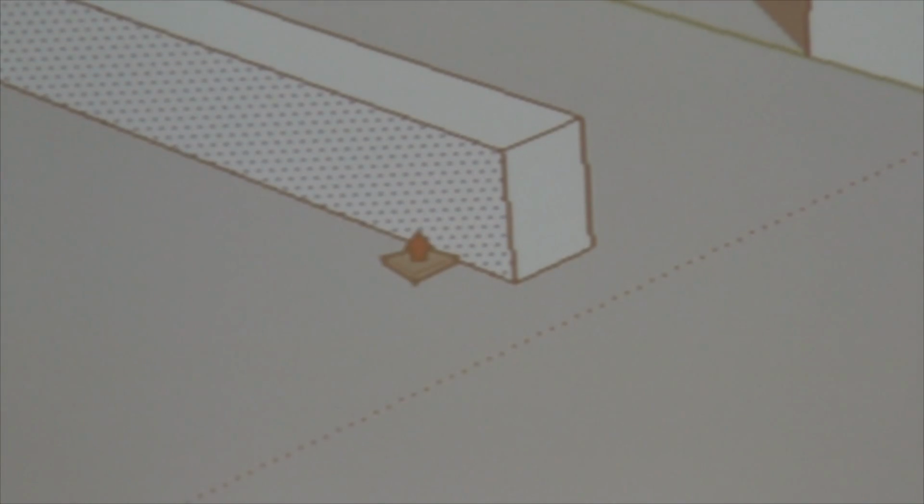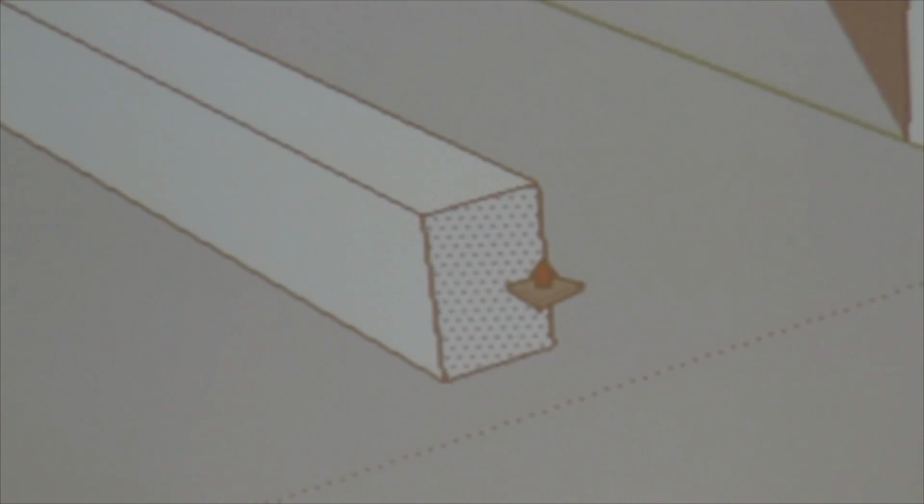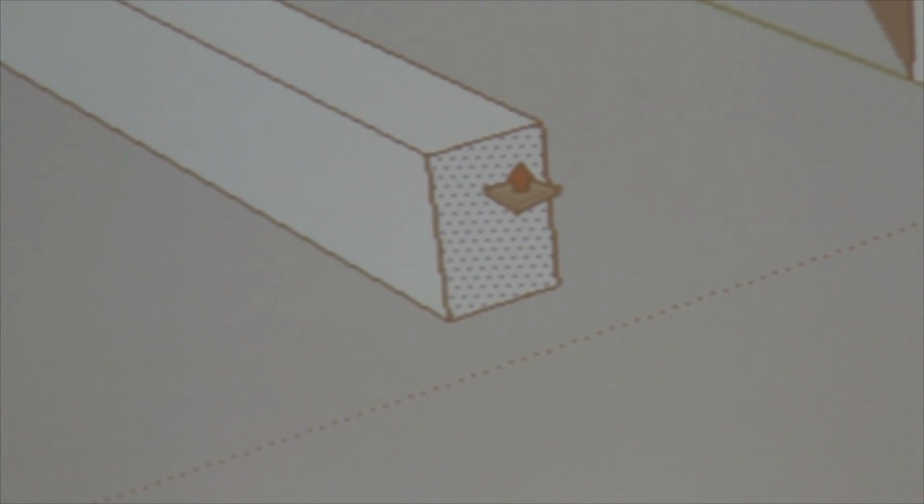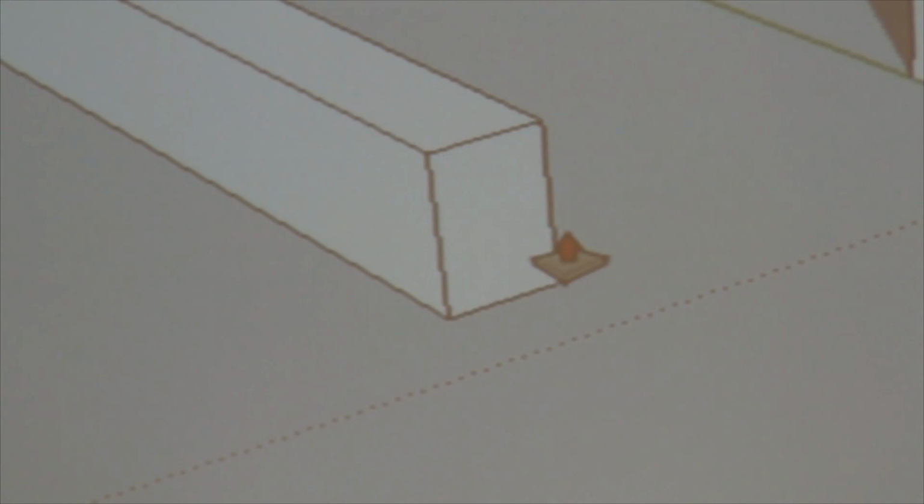And from there, I'm going to cut a tongue on either end of this, because we're going to actually put the tongues into the slots in here. I'm going to do a full height, 1/2 inch deep, 1/4 inch from the outside edge, 1/4 inch thick tongue.